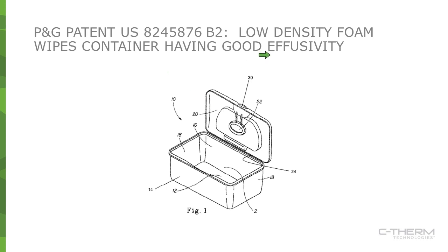I find this title kind of interesting. I wouldn't normally describe effusivity as good or bad. It's dependent on the application. In some cases, we want a high effusivity. If you're targeting technical apparel for summer application, you want a nice, cool feeling material. There, you're going to want to have a high effusivity. But in the winter, of course,